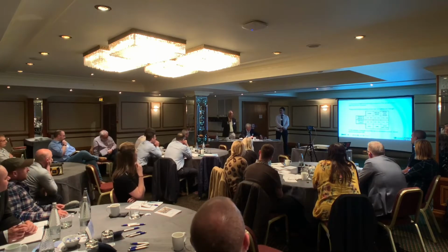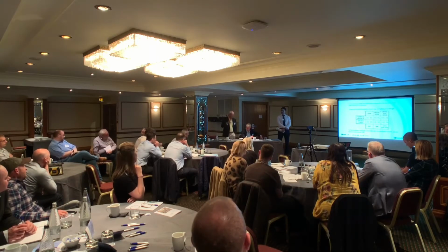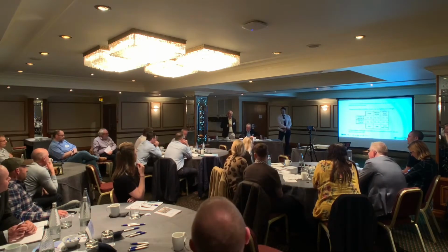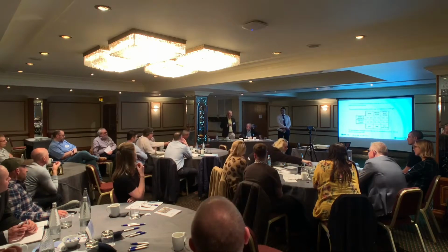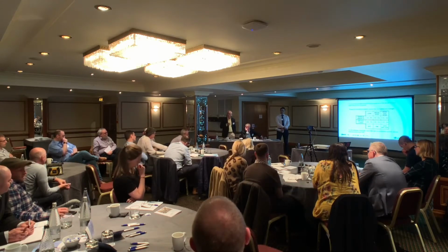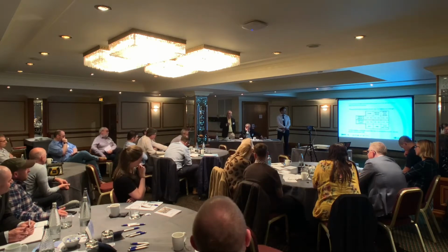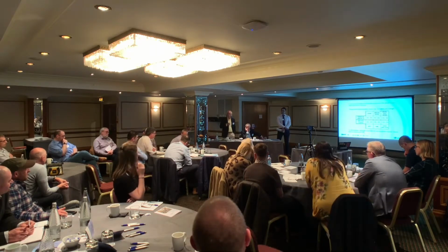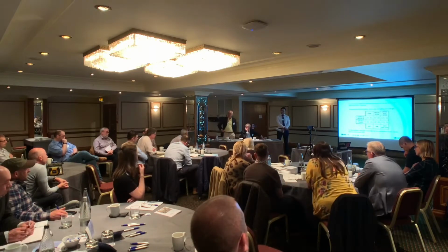Can I just ask a question in relation to this, which might apply to contractors? How can you adjust the way you operate your machine to control heave and settlement? Because I'm sure that comes into it as well. Pick the right type of machine. Pick the right method you're going to use to excavate the soil. There are lots of different versions of soil conditioning and pressures you could use, and as mentioned, driving styles, which can produce more or less settlement.